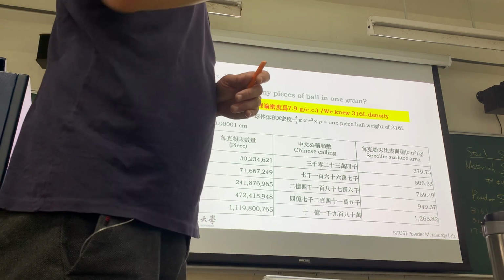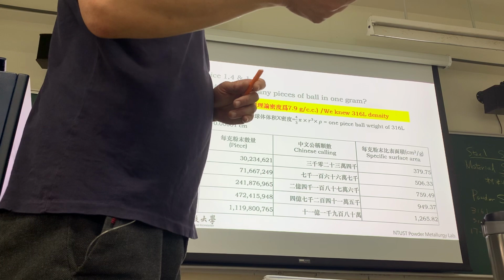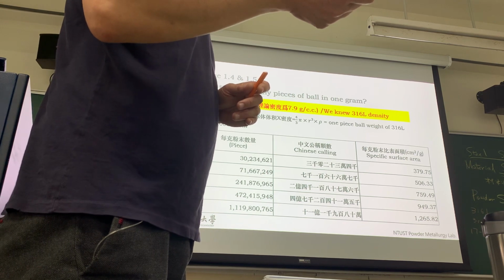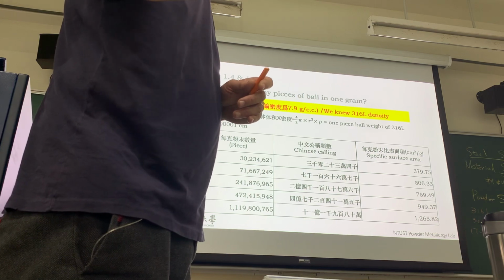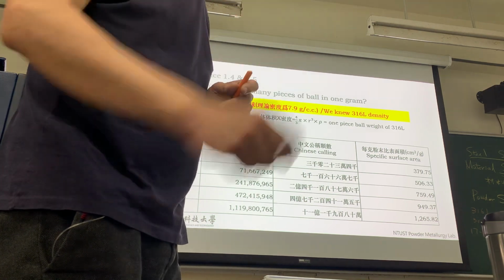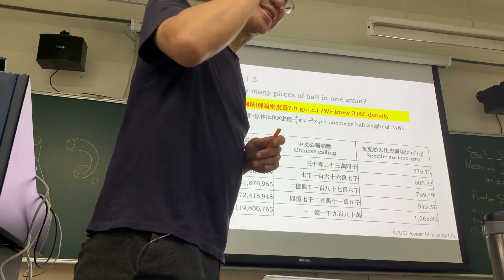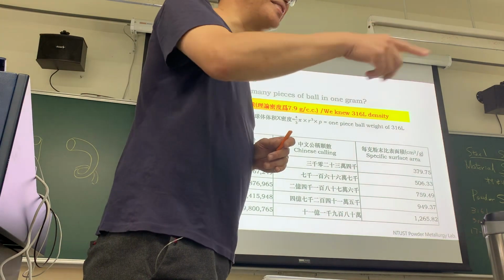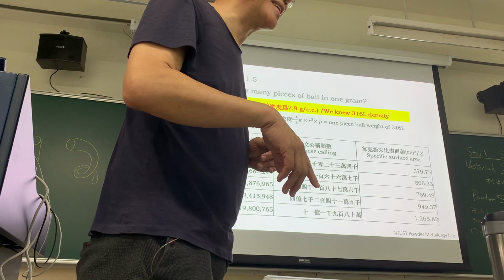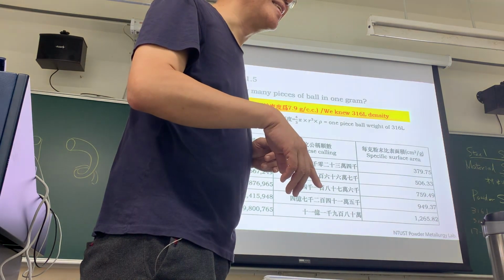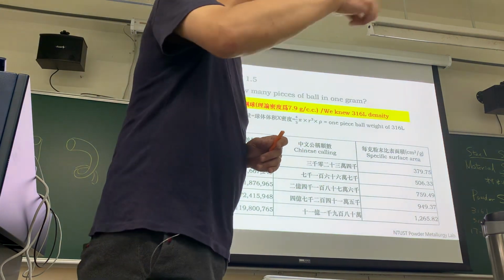Just like in your future tests, if you want to use zirconia powder, it is always 0.3 to 0.5 micron per piece, and you want to add it to metal powder of about 16 to 17 microns. That is 100 times different.